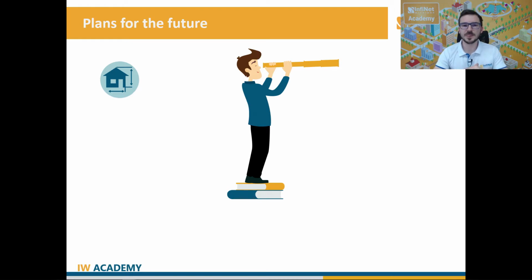And in some cases, you might have a tall building between your sites, and you want to know exactly how that obstacle influences the performance of your link. And this feature will allow you to do just that. So add manually an object on the map, and then InfiPLANNER will take into account the influence of that object on the performance of your link.